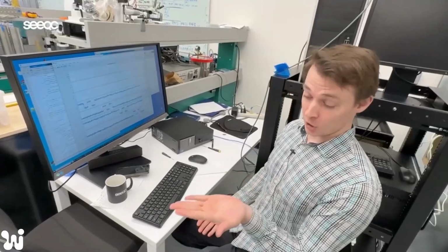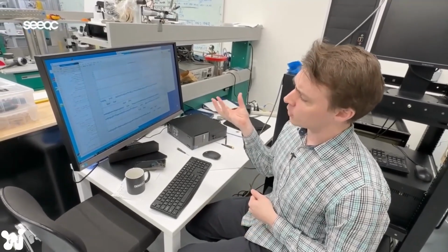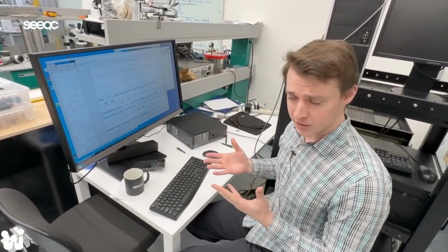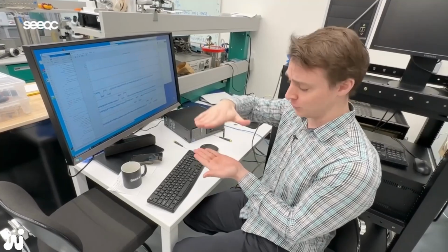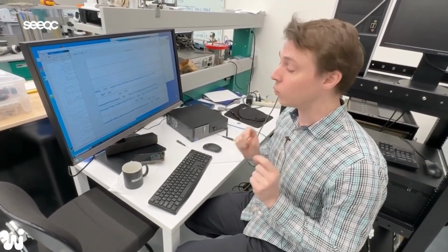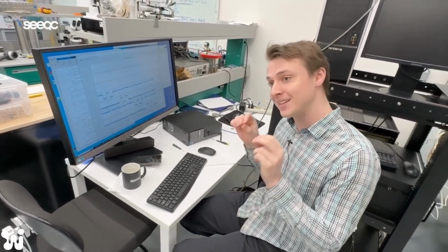This is our large bottom chip that has all of our SFQ control circuitry, and then we take a smaller flip chip that has our qubits and quantum circuits on it, and we physically squeeze them together with specific lines so they can communicate and be magnetically coupled. Then by only accessing our control circuitry, we can communicate, modulate, and set the qubits, the quantum circuitry, without physically directly communicating with the qubits themselves.